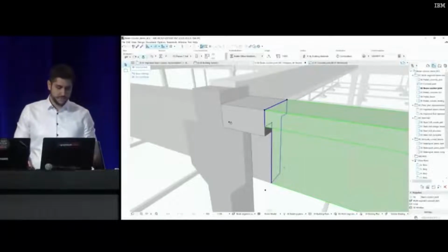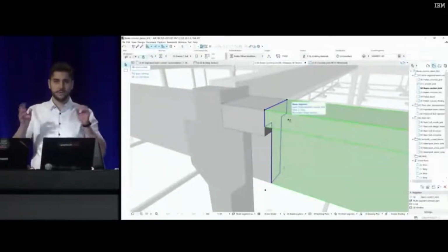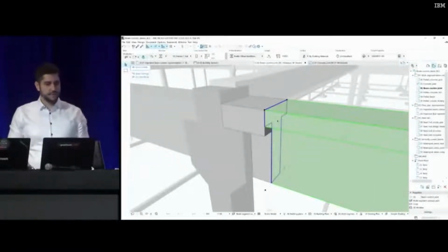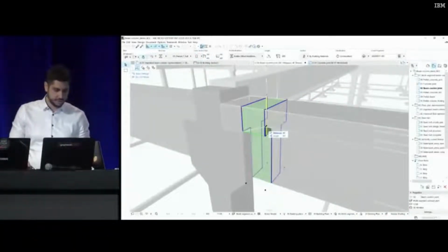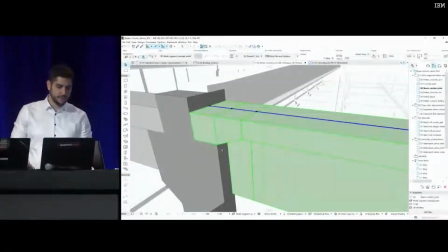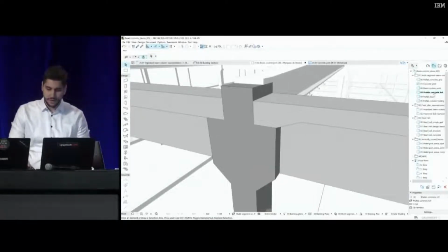But right now, I have 2 different versions of the same parametric complex profile on these 2 parts. Now, how could I bridge the gap? By combining the tapered segment capability with parametric complex profiles, I can get a real smooth transition between these 2 segments, allowing me to create such connections.